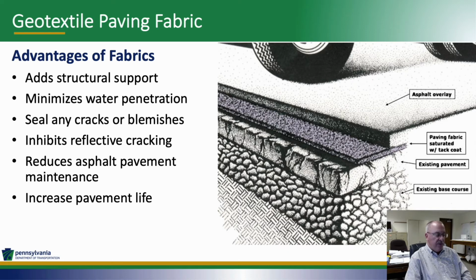Paving fabrics are easy to install on both milled surfaces and on roads with curves. It's probably one of the easiest interlayers to install. Fabrics can be milled and recycled with conventional milling machines, and fabrics are chemical resistant to road salt and other chemical de-icing agents.